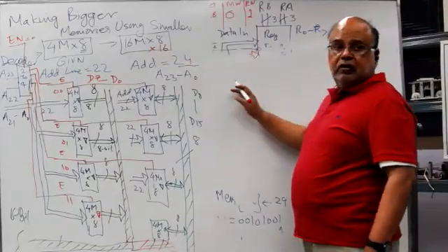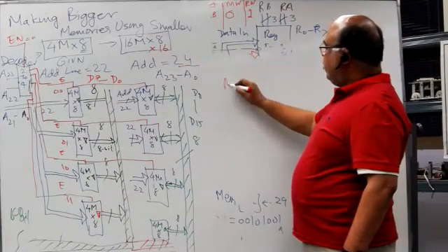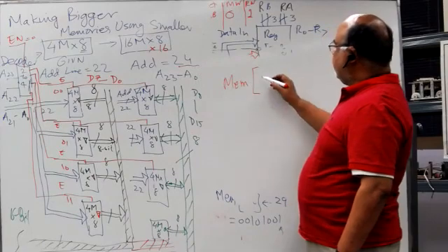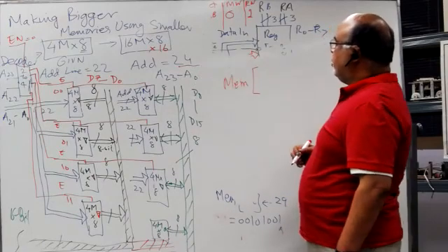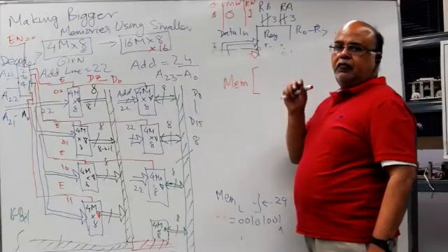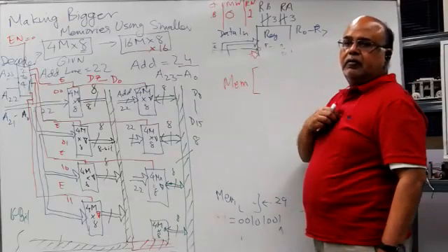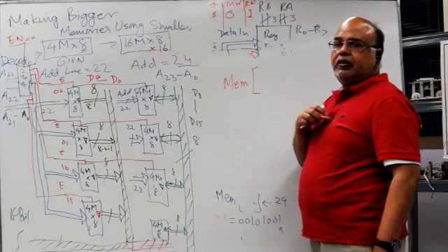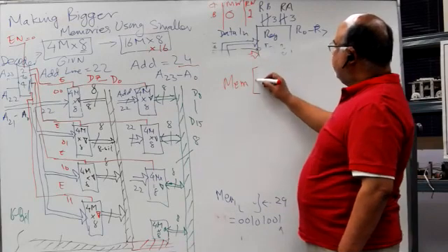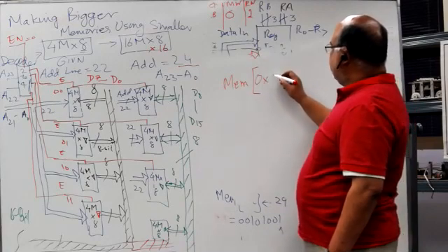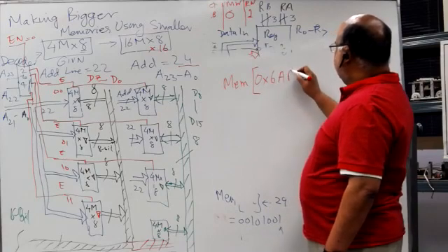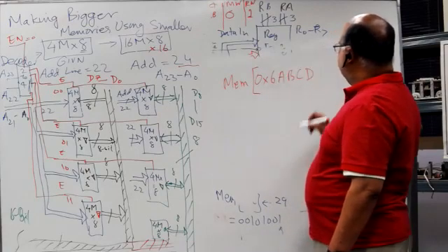If I give an address, so this is a 24-bit address, means a 24-bit pointer. If I give memory a direct address, no register, a direct 24-bit address, how many hex digits will that be? How many hex digits are there in 24? Divide by 4. 6 hex digits. So let's say I'm storing this on this memory location, 6 A, B, C, D.